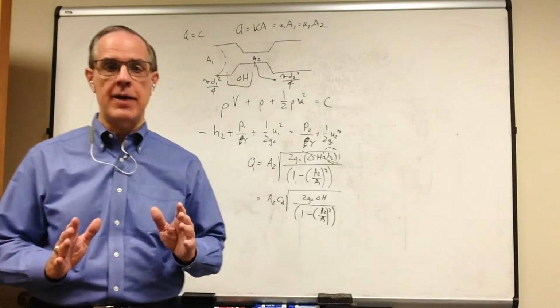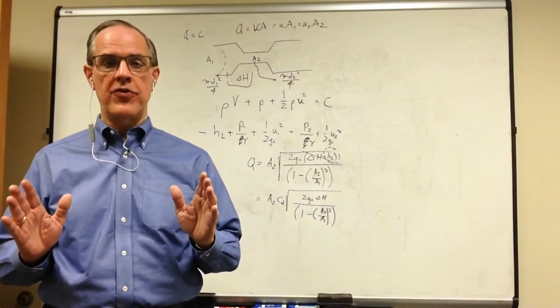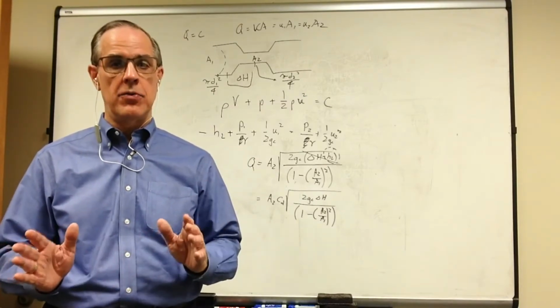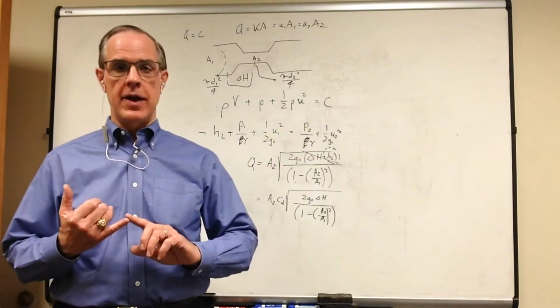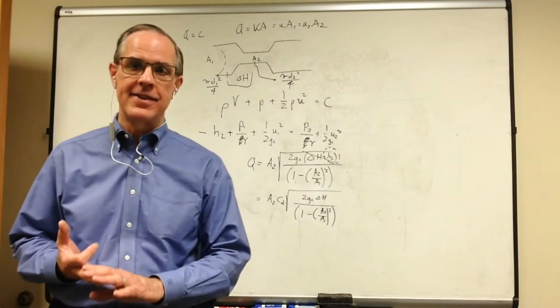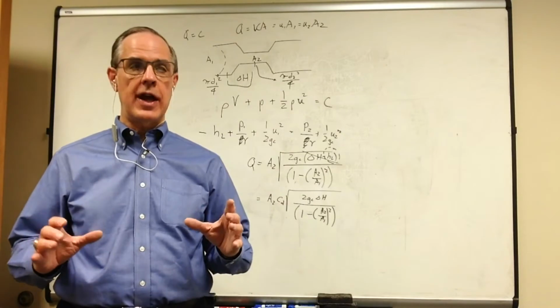And I've seen this happen. But before we start figuring out how to get rid of the minor losses, we have to explain what they are. Minor losses take place when we have valves in the system, elbows, T's, or other restrictions in the line, such as changes in diameter, for example.